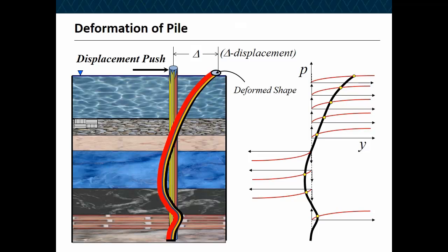What I have done in the current model I'm going to show you in Midas, I did not linearize anything. Just like the abutments, I used full nonlinear springs along the pile in the finite element model in Midas.